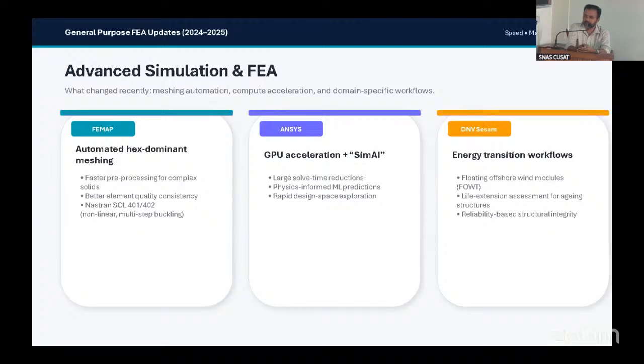the longitudinal bending and the shear stresses were exceeding, and they had to put some additional thickness, or additional walls over there. The structure people, when they're doing the structural work, it's an empty area. You can put as many bulkheads as you want; nobody cares about that. But when it goes to real production, when you talk about your arrangement of machinery and all, you cannot have a bulkhead in the center of your engine. I'm just giving a crude example, nothing like that happened.